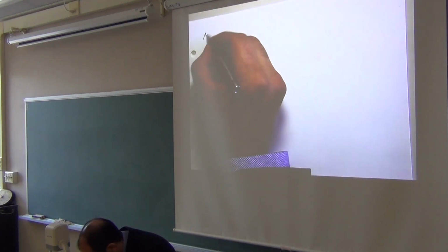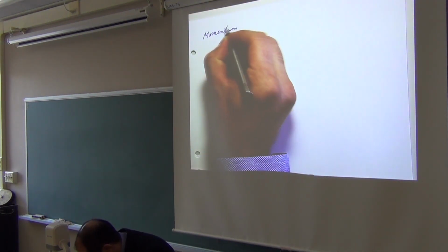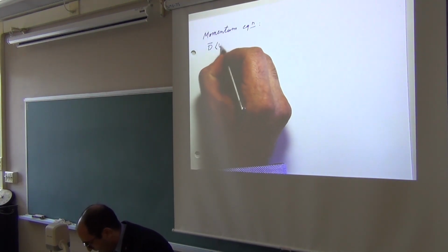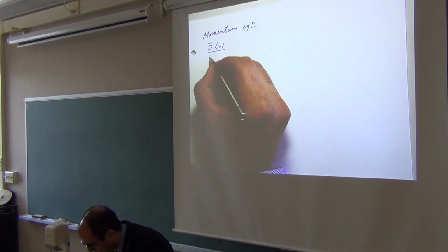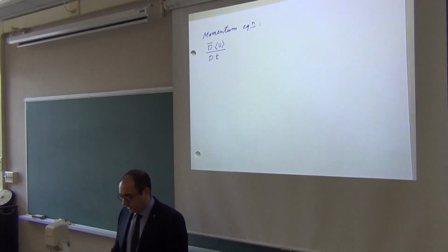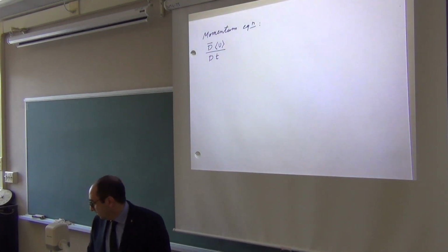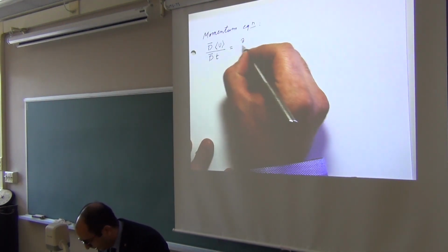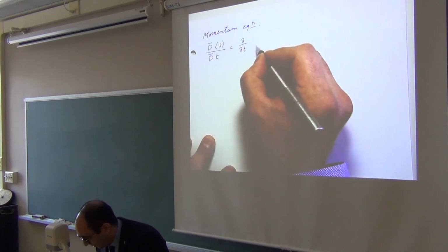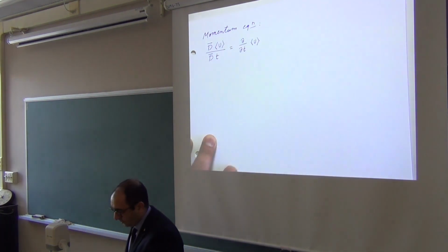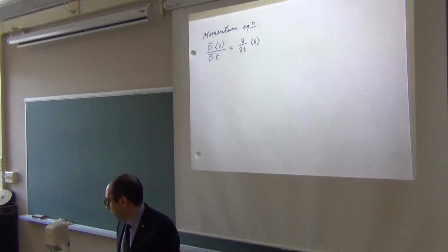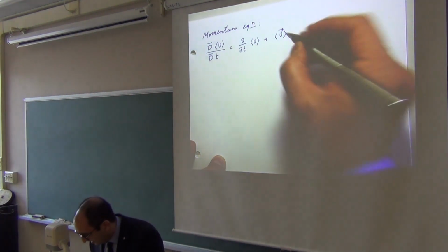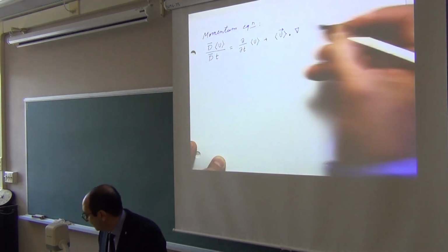Momentum equation. If you recall this symbol, this was always on the left-hand side of the Navier-Stokes equations. It's the derivative of the mean. And by definition, it's the partial derivative with respect to time of the quantity of interest, in this case momentum, plus the mean momentum vector dot product with the gradient of the quantity of interest.